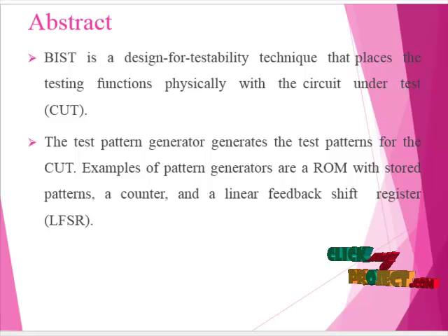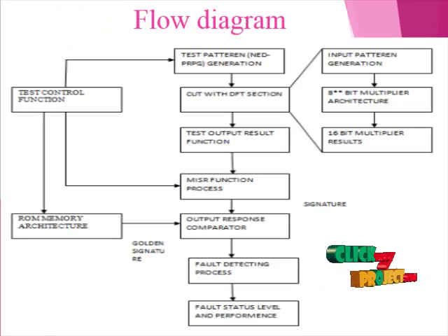Gated scan cells are also proposed. A synergetic test power reduction method uses available on-chip clock gating circuitry to selectively block scan chains while employing test scheduling and planning to further decrease BIST power in the cell processor. Next, we are going to see the flow diagram for our product.